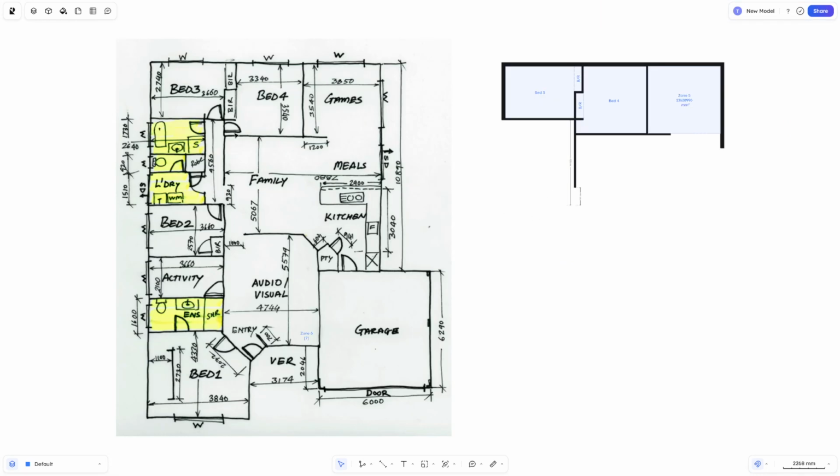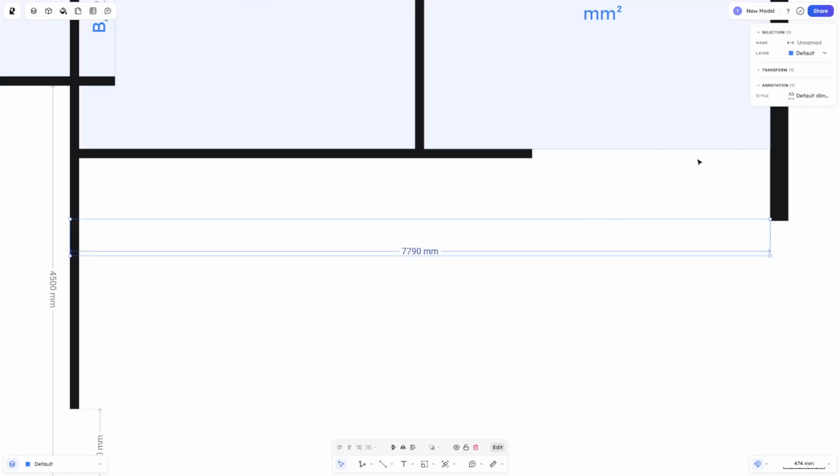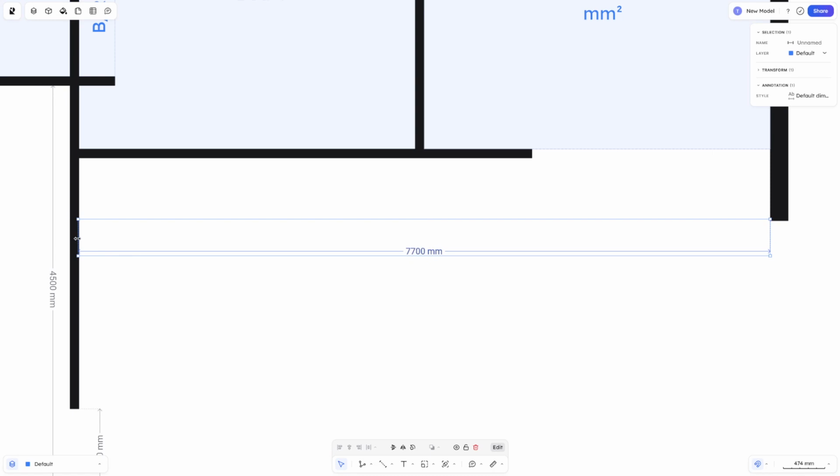So if we shift F back out, so here we've just drawn this section of wall in here. We've got this bit already, got this length of wall. So we now know we can draw a zone that is 7,880, although it's upside down, 7,880 this way, which should be the exact distance from here to here. So let's just double check that. Let's see. Oh, slightly, it's because here. So this is going to be to there.